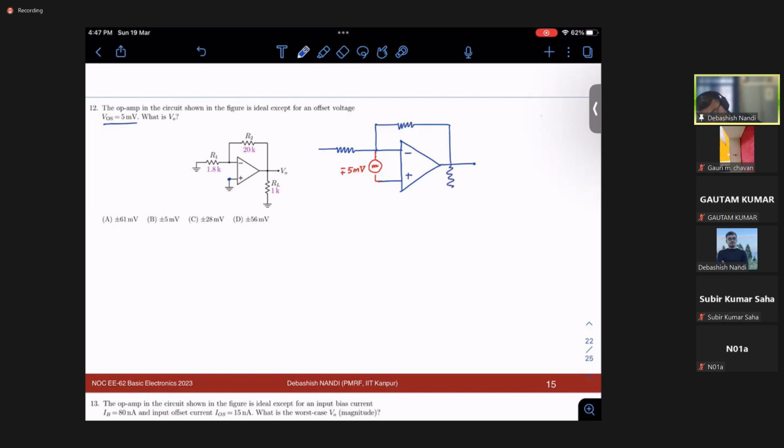So you see, you will eventually have an operation of differential nature because you have some input voltage difference, right? Even though your input terminals are grounded after all, you have a difference voltage due to the offset or the mismatch in the two pairs of the differential amplifier. You have a mismatch, and that is translated as an offset voltage at the input between two terminals.